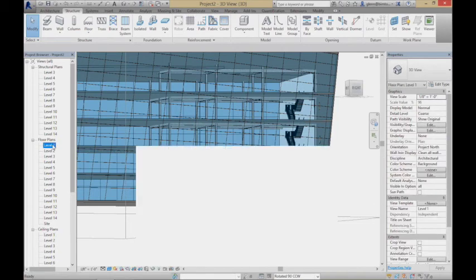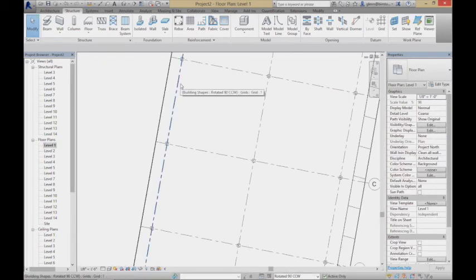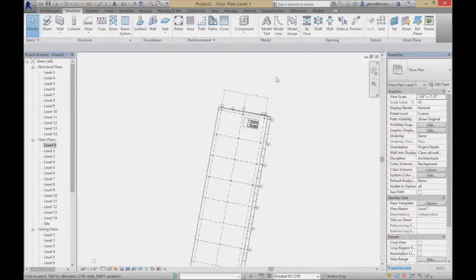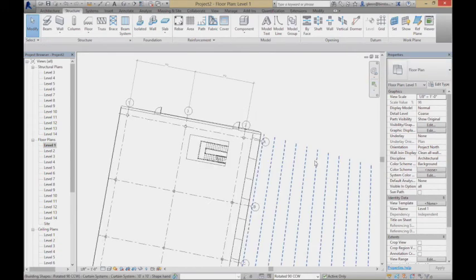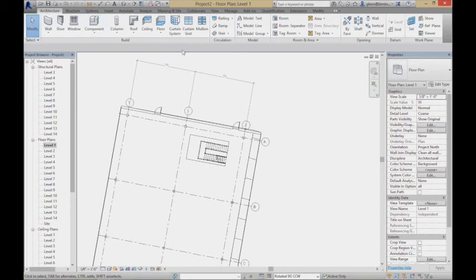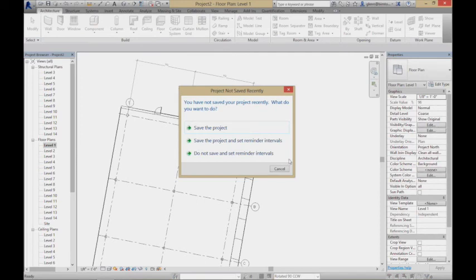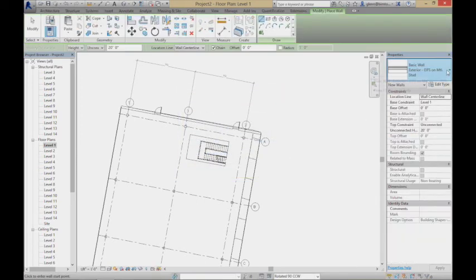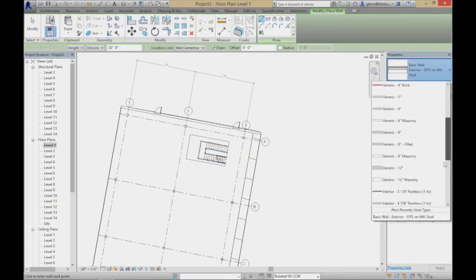We've been creating all this stuff and putting our structure in. And I'm hoping you're getting the sense that it's really not too bad, in terms of the type of modeling we're doing right now, it's really back to doing the detailed modeling that we have been doing. So if I want to put in some walls on the inside of the building, I could choose the wall tool, choose a type, just like we have been doing.